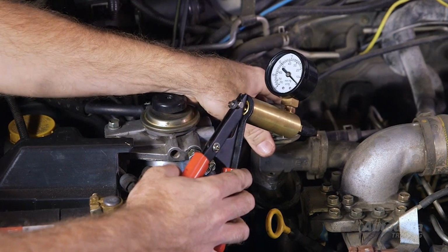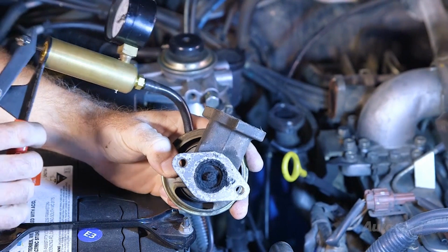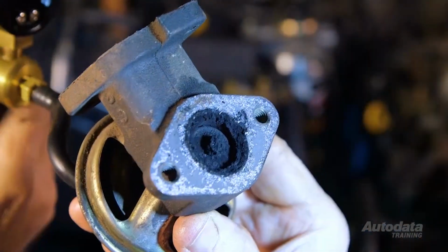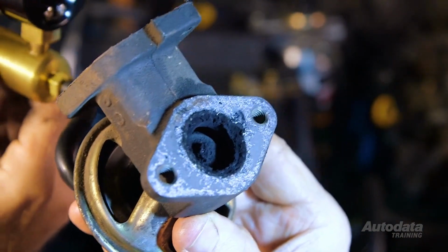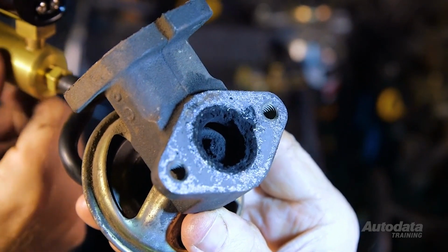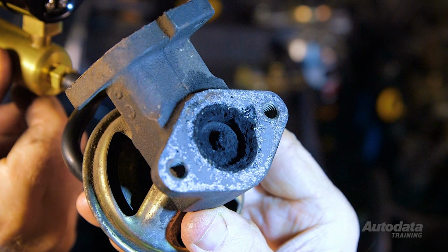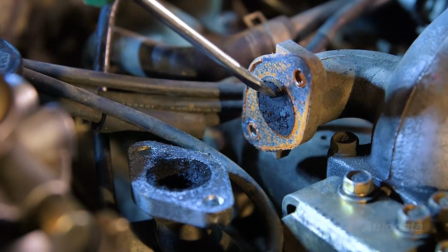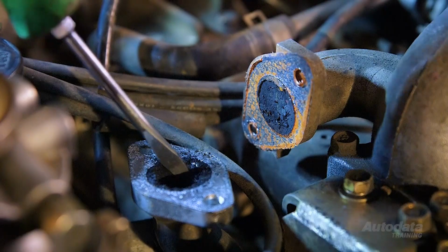If no change occurs, it will be necessary to remove the EGR valve and operate the hand vacuum pump while observing the pintle. You should see the valve open as vacuum is applied. When the vacuum is released, the pintle should close smoothly. Be sure to inspect for any carbon or debris build-up that may prevent the valve from moving. Inspect the EGR feed pipe and intake manifold port for blockages, as this will reduce EGR flow.